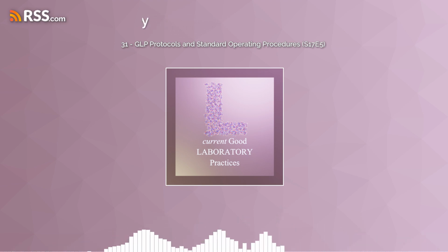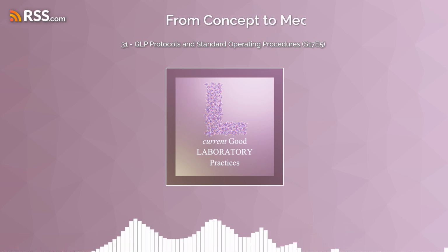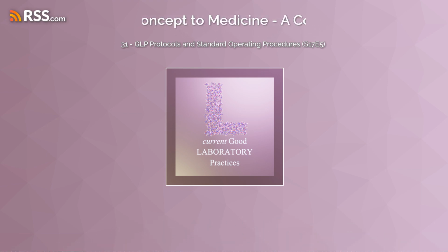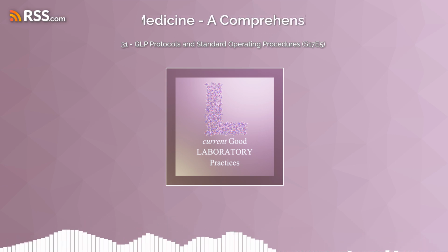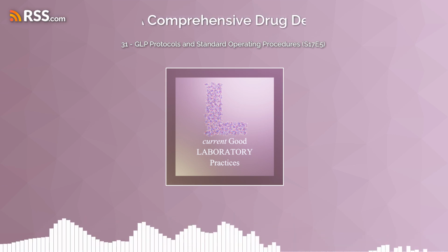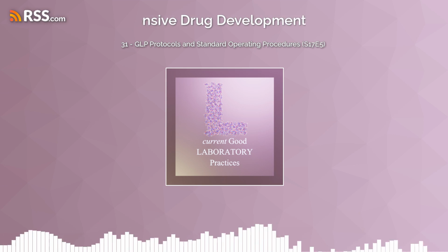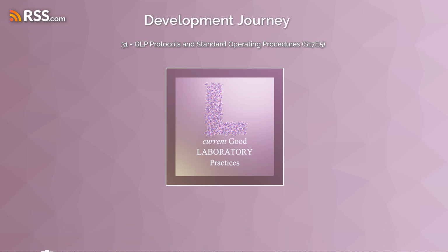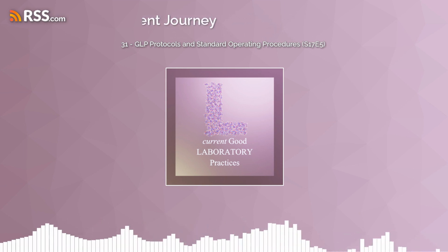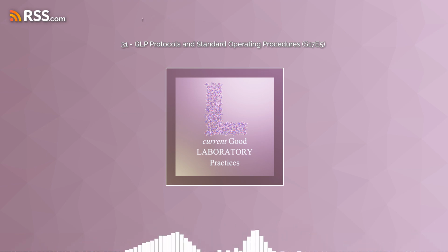And just like with qualification, all those calibration activities need to be logged in detail, including the dates, the methods used, and of course, the results. So, if I'm understanding this right, qualification is kind of like making sure the instrument is fundamentally sound and set up the right way, while calibration is like fine-tuning it to ensure those numbers it spits out are actually correct. Yeah, that's a really clear way to think about it.